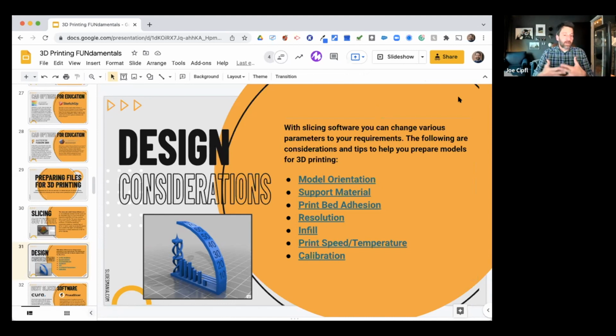So when you first start 3D printing, and you open an object in your slicing software, there are default settings. So you can just go with the default settings for PLA filament and then start your printing process. And then as you get the hang of things, you can start to make little tweaks to improve the quality of your prints. So print with the default settings at first, learn the process, and then you can start making little tweaks like, oh my gosh, I noticed some stringing happening on that print. So I'm going to dial down the temperature just a little bit.